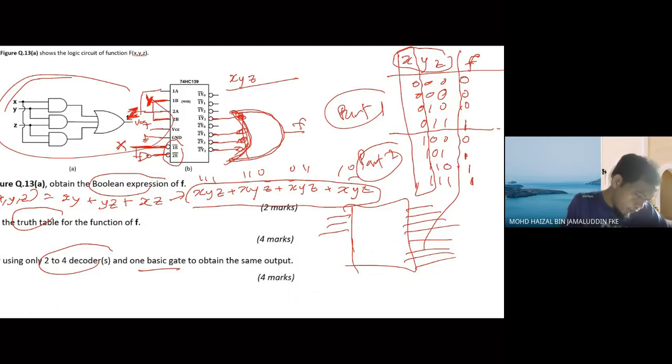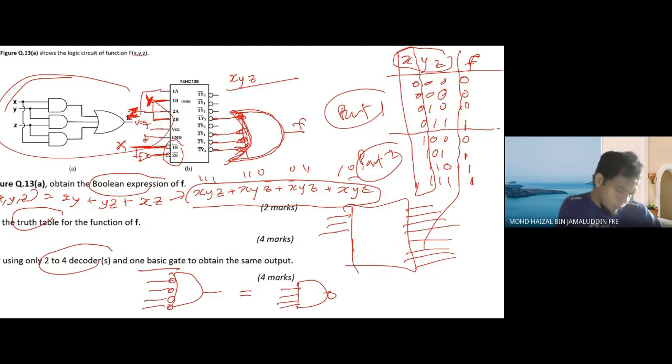So then a NOT gate. And actually, when you have it like this, the 4 bubbles of the gate are equivalent to a single NAND gate with 4 inputs. Okay, so you need to replace this with this, right?